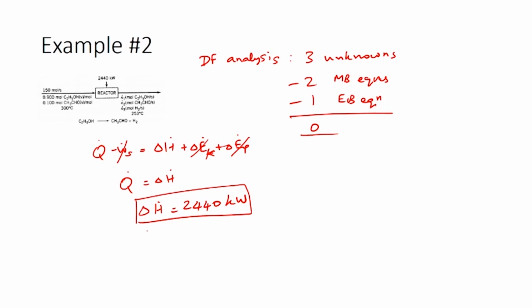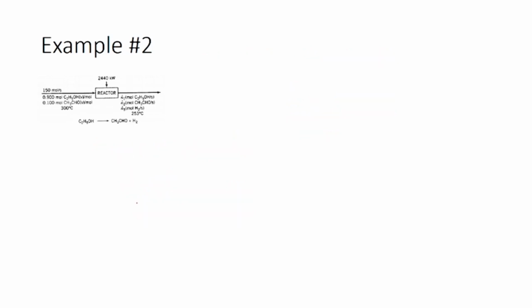For that we would have to build the enthalpy table. So, let us identify the reference state which we would want to use. Here I have used the elements as the reference state, so that I can use the heat of formation method. The reference state would be carbon solid, hydrogen gas and oxygen gas, all at 25 degrees Celsius and 1 atmosphere.